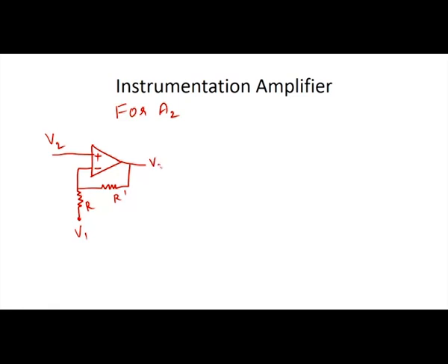Here the output voltage is considered as V2 dash, which is the summation of V03 plus V04. So we again have V2 and V1, the two input voltages. Again using the superposition theorem, we have to find out V03 keeping only one voltage given to the circuit and the other voltage 0.